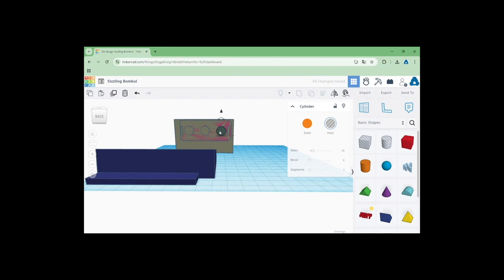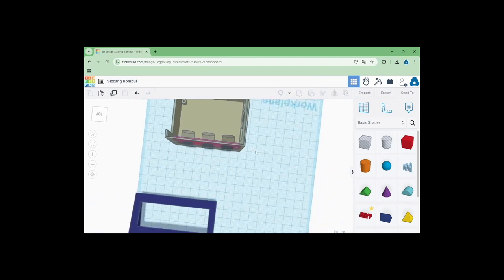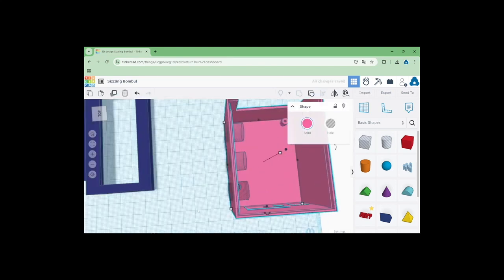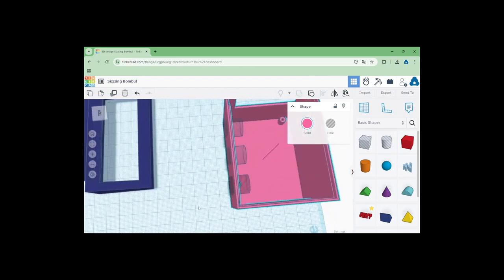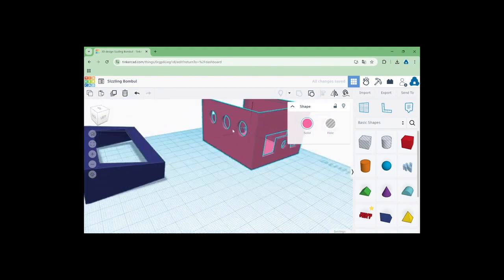Make a copy, paste, and I will move this to this hollow, and paste, and I will move it to this hollow. Then, as you know, these elements are transparent, which means that if I try to join, it will make the hollows. First I will use these two elements, and I will join both. It means that I integrate this position. And now I will do that, elements I will join again. And that's why I have the hollows